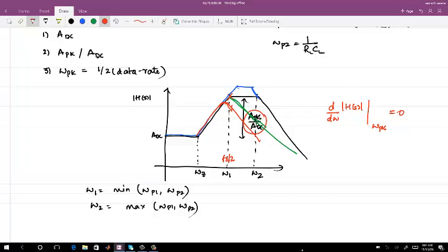Doing it this way systematically, at least you can get a first assumption of what the pole and zero locations should be, and then you can start using the other parameters. And the main goal is that this should be a minimum power design, because power is the cost here. If someone says I want a 10 dB gain at 20 gigahertz, if I have infinite power, I may be able to do it. But if the CTLE power consumption dominates the whole power consumption, then it's surely not a good design.